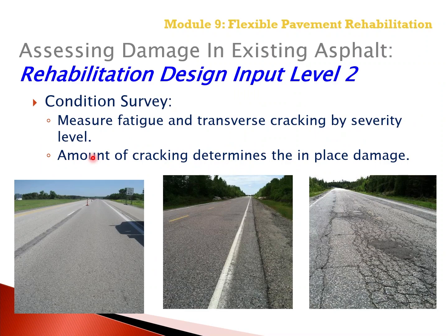So now let's move to rehabilitation design input level 2. For input level 2 for rehabilitation design, the results from the condition survey are used to define the in-place fatigue damage of the existing asphalt pavement and/or layers. So we're measuring the amount of bottom-up fatigue cracking and the length of transverse cracking and defining it by severity level.